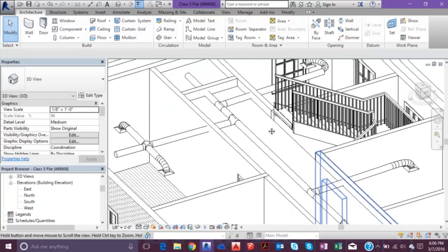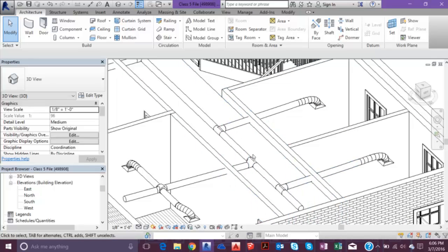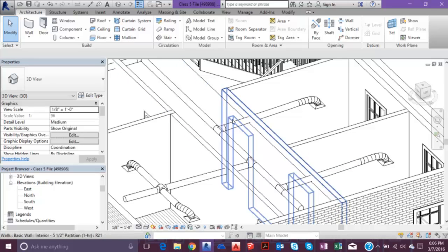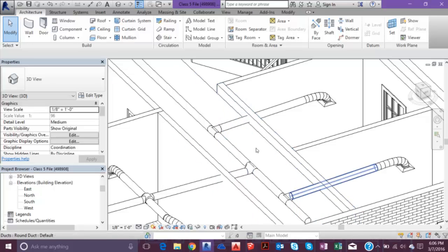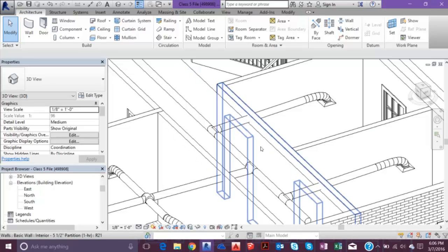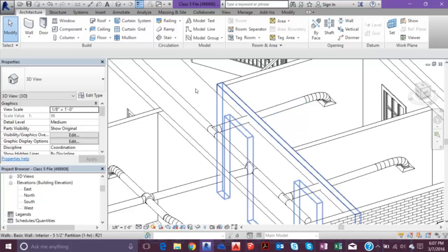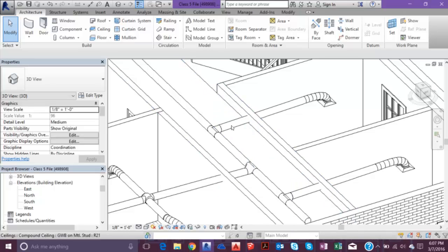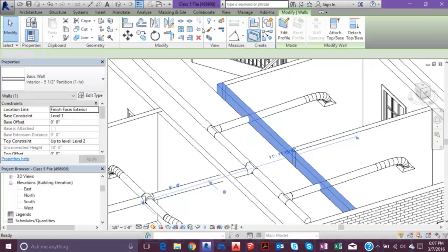And I encountered an error, or really a problem, in the last video with this because I was trying to add another hole over here. What I found when we go to divide the parts and make that hole in the wall, this one wall is a part, well, really an element in itself. So I can only get like the first layer of the parts to just the drywall over here, and it wouldn't keep on going through the rest of the wall. When we exclude our parts, we have to actually exclude it all the way through the entirety of the wall. Through both sections, and so that will exclude that part. So let's go ahead and create a part out of this wall.